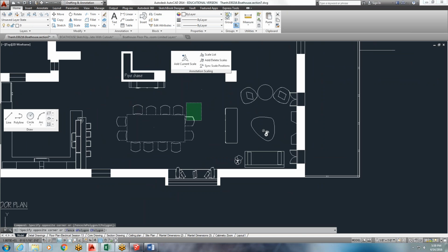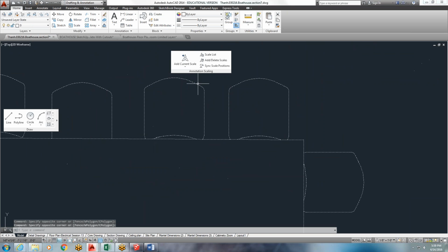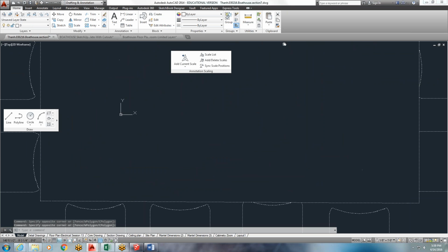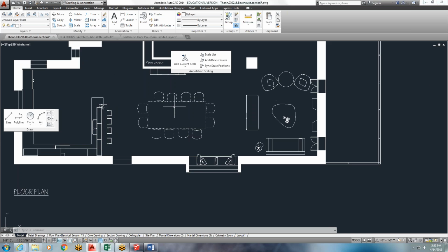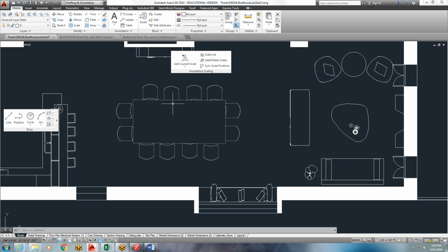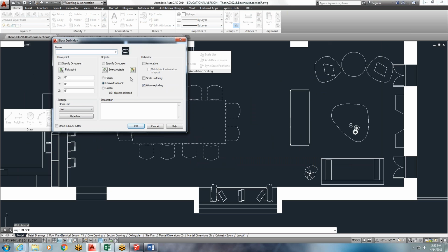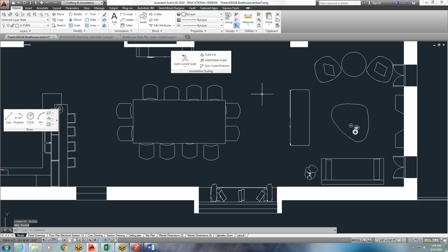and then make sure you have all the lines. You could see some of them are not selected. All right, looks like I've crossed over all of them. They just look a little goofy out here. And I type in block and let it think about it. And then I'm going to go ahead and type dining table and enter and let it think about it for a minute.